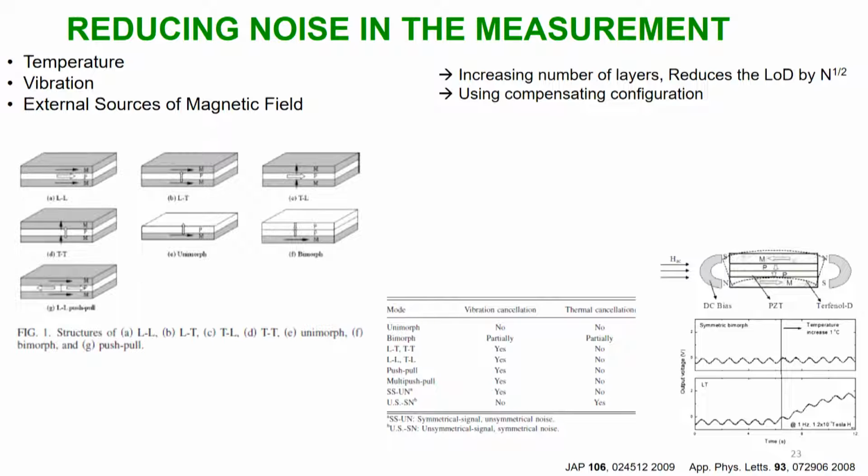People generally get a particular variation, where with temperature and with time the potential goes on increasing or decreasing. That can be avoided by taking two such setups and compensating. In case you are not able to do the symmetric, take asymmetric, but make two identical devices and compensate. I think people can do that. So, as I mentioned, the symmetric structure and the asymmetric structure affect this differently.